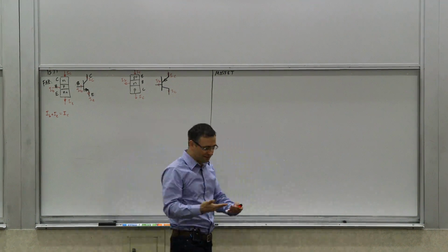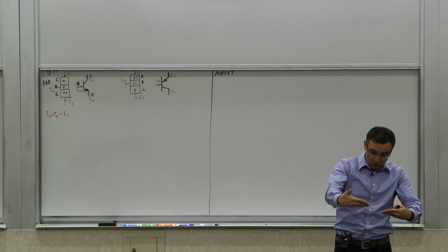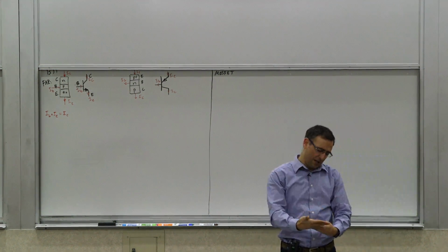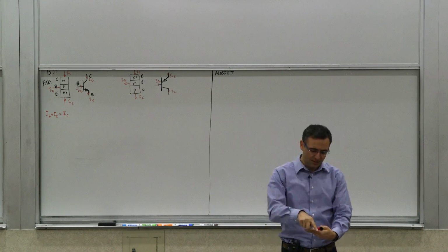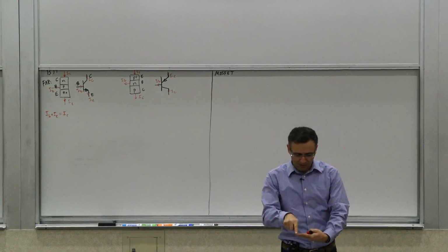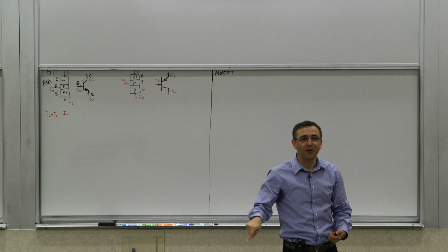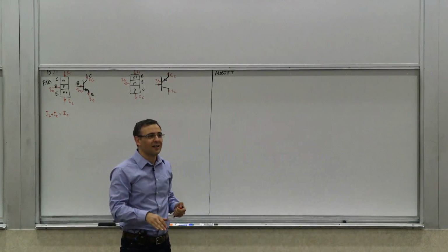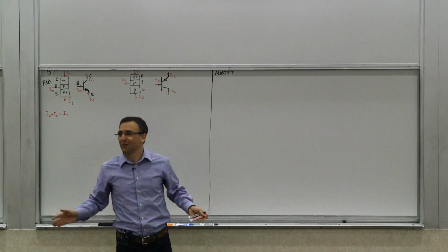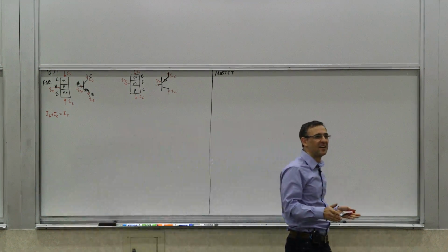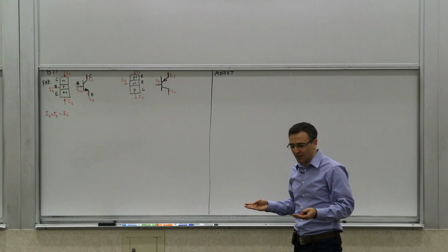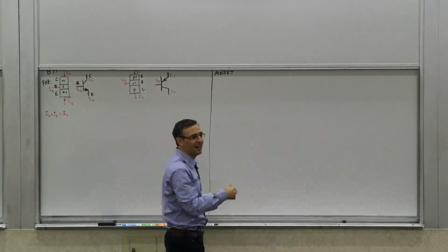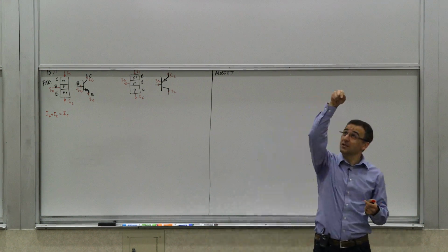So I said, let me see. The schematics were 2 sheets, not 1 sheet. I mean, it wouldn't fit on 1 sheet. I looked at them. So this transistor is off. This one's off. This one's off. This one's off. So I went through all of them. So out of the 200, let's say 200, if it's more than 200, 196 of them were off. And there were 4 transistors. 2 of them had formed a basic cascode, which we'll talk about. And the other 2 were 2 diodes shorting the supply to ground.